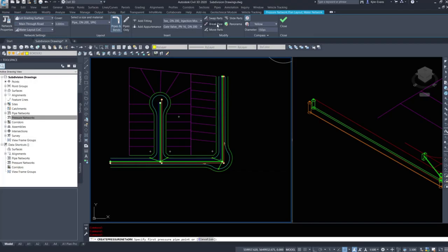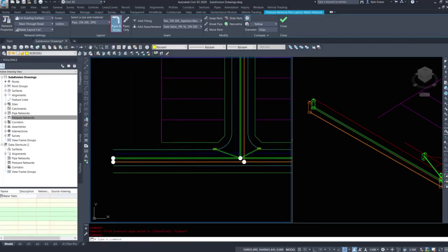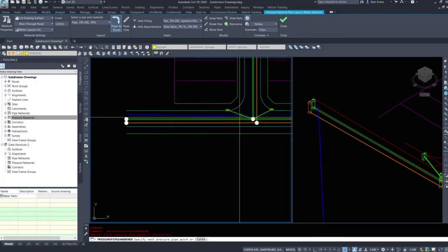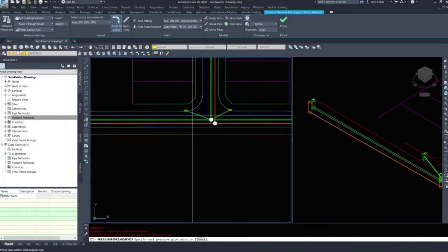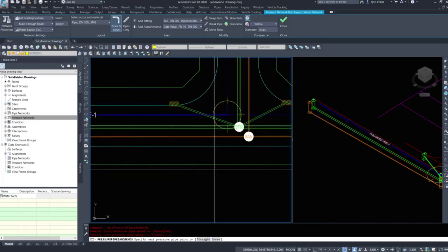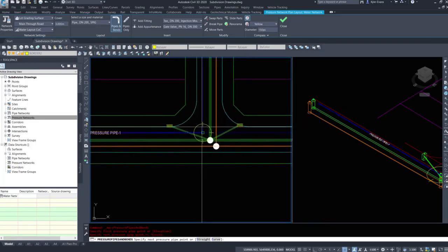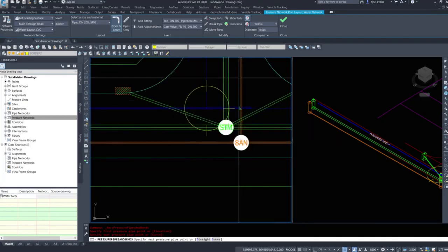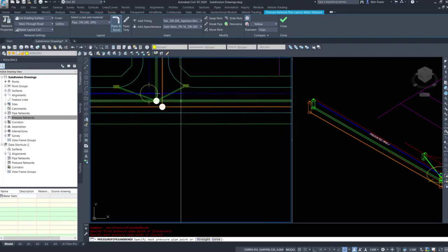We can swap parts, break pipes, we can move things, we can slide them around, we can look at it in a panorama view. However, I'm just going to start drawing pipes and bends. Draw pipes and bends. So I'm going to draw it from here. And as we see over here, it's updating to that location. Now, because we specified a T, Civil 3D only lets us go to the right, and it's not even applying that 5-degree deflection, or to the north.